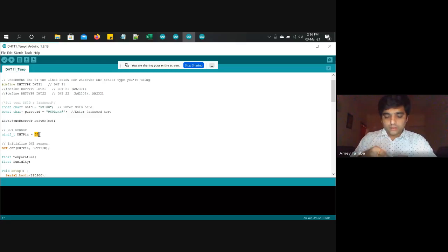So the plus one, I'll just disconnect first, will go to 3.3, as NodeMCU has all 3.3 outs. It does not have any 5 volt out. So it has almost four 3.3 outs. I have one of the 3.3 outs here. So there is no pin left.